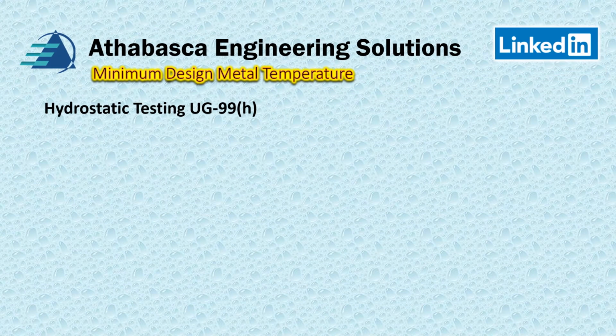Move on to hydrotesting. This is one of the most important parts in the code. It's with regards to making sure that you're not hydrotesting at a temperature below your MDMT. And of course, the implications of hydrotesting below the MDMT temperature is that you could have a brittle failure of your vessel. And that can occur in the field or in the shop. And there's a part in fitness for service where they actually do evaluations to make sure that they're not hydrotesting below that.